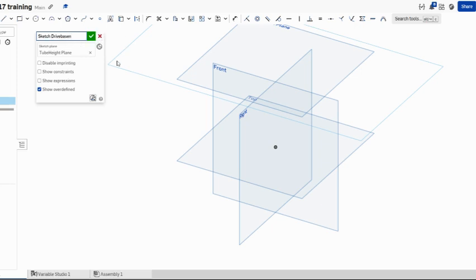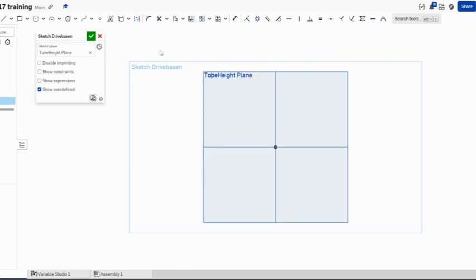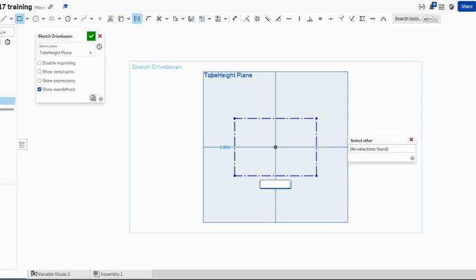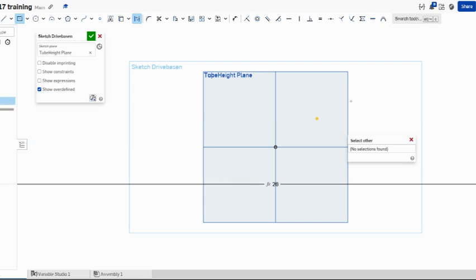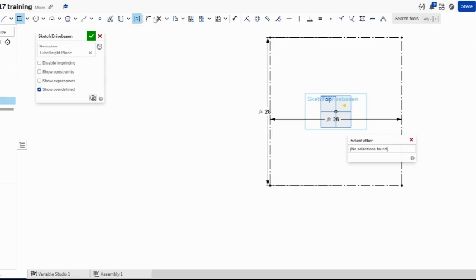The letter N normalizes my view. And I'm just going to create a corner rectangle that is a construction. So it's centered on the origin. And then this part that's the front, if I just type a number in backspace, now I can do number sign, and I can easily select my variable. So same thing for the sides. And there we go. So now I have a rectangle that defines my perimeter.